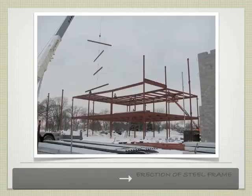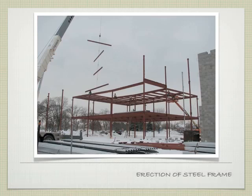The other thing about it is if you're using a crane and you have all these repeat elements that you're going to use over and over again, it's a whole lot more time to pick up one piece, put it into place, go back and pick up the second one, put it into place. So what they'll do is chain these together. The crane will take 4, 5, 6 of these beams, joists, girders, chain them together, and then one time they'll lift from the yard up onto this section of floor, and they'll use the first one, lower down, use the second one. So you can see there's an efficiency to it.